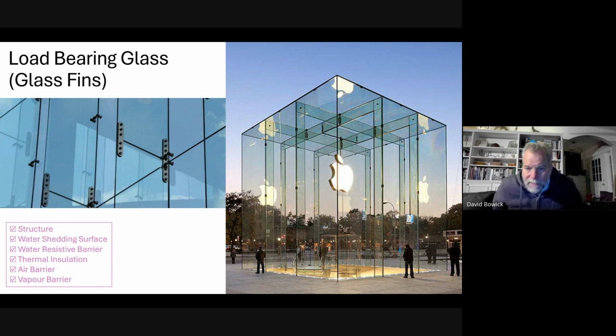So where we've got the glazing sitting on top of the load-bearing glass walls, it probably is the same. We've got a couple of setting blocks in the corners. The glazing sits on that. There is a silicone joint, but the silicone joint is there to hold it together and keep water out. It's not intended to be the primary load-bearing element.